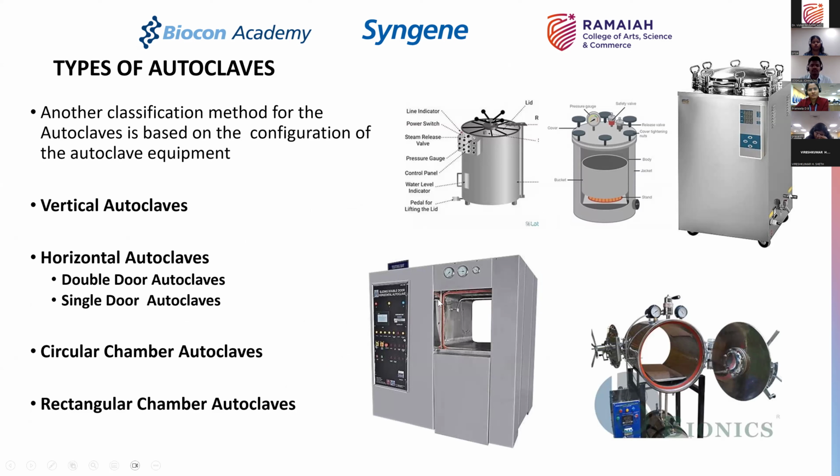When you have a very large autoclave, like 2000 liters, 3000 liter autoclaves, these rings become really difficult, because the whole part has to be machined. Look, when you have a smaller rectangular chamber, from a fabrication perspective, machining is easier. When you have a very large autoclave, machining is a difficult task, and sometimes it is difficult to get perfect lines or squares, sorry, perfect lines parallel to each other to be able to fit the rings. The gaps can sometimes be there.